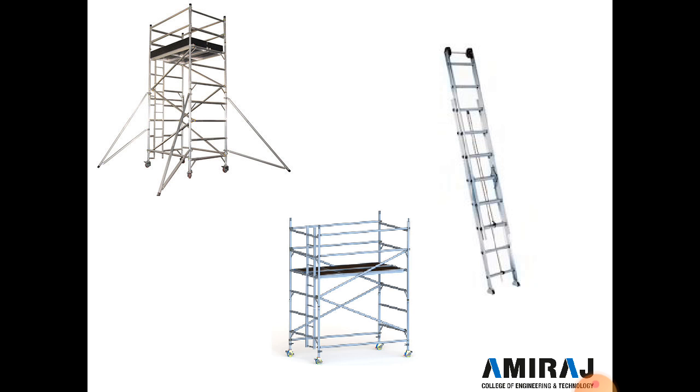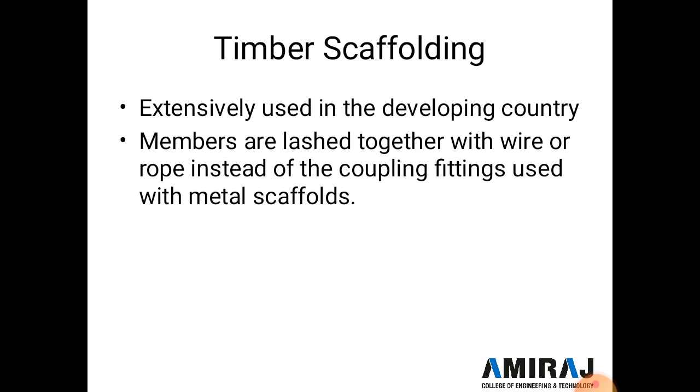So this type of platform is made by the aluminum section. Now the third type of scaffolding is timber scaffolding. It is extensively used in developing countries, and timber scaffolding is generally used because it is easily available. Second, the cost of timber scaffolding is less as compared to aluminum and steel sections, and members are lashed together with a wire or rope instead of the coupling fittings used in metal scaffolding.